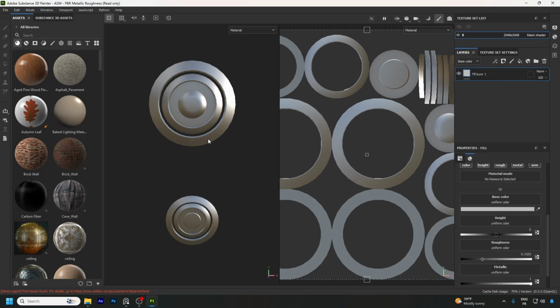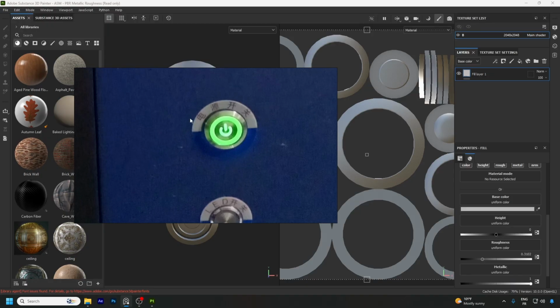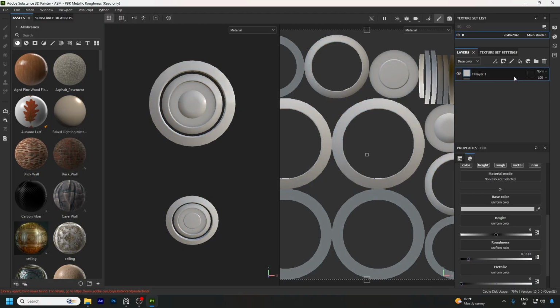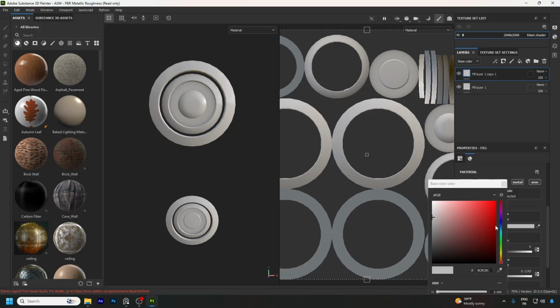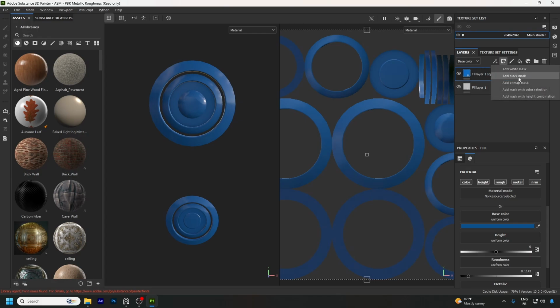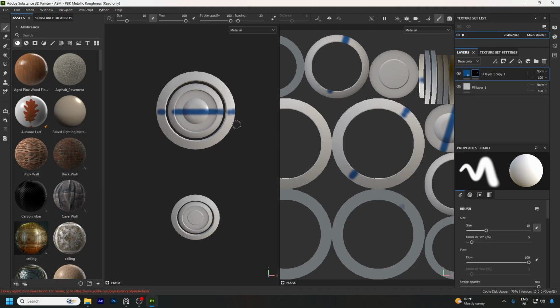What I did also is bake them. You can look on YouTube for how to use Substance Painter. Anyways, look, we have two types of texture. One is white, one is blue, and we can reduce the metallic to 0, add a bit of roughness, duplicate the fill and make it blue. That would be great. Then, just with the black masks, we can have something like this.